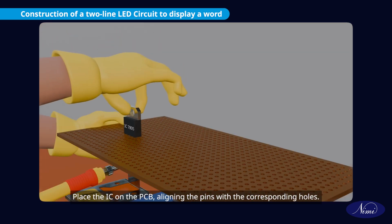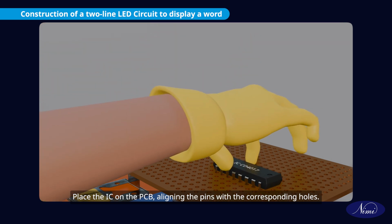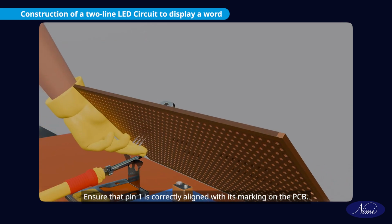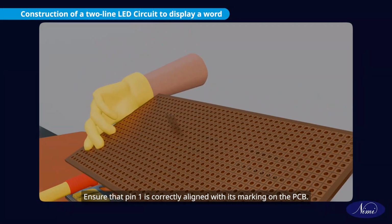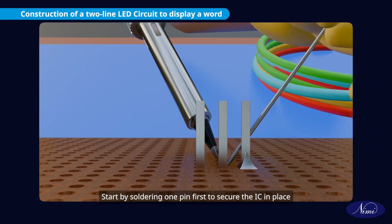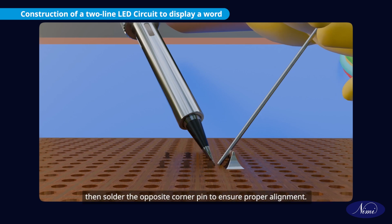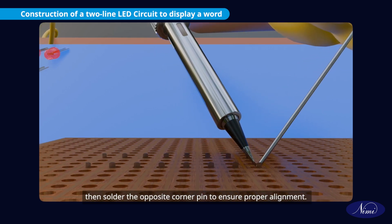Place the IC on the PCB, aligning the pins with the corresponding holes. Ensure that pin 1 is correctly aligned with its marking on the PCB. Start by soldering one pin first to secure the IC in place. Then solder the opposite corner pin to ensure proper alignment.